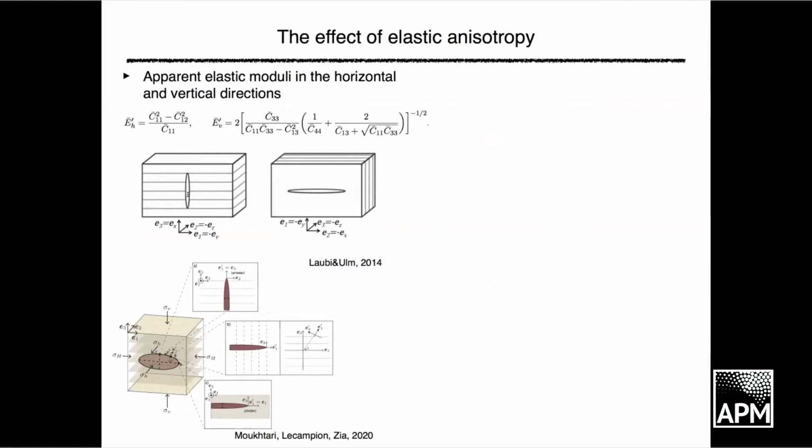And they concluded that, if you open a fracture in a direction perpendicular to the layers, in this way, right? So think about you have a 3D fracture, you have side view and top view here. You're going to see a different apparent elastic moduli, right? So if you had isotropic material, then all these would be the same, right? But because it's anisotropic, they're slightly different.